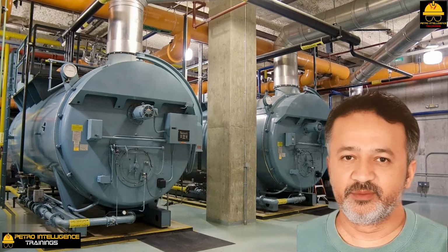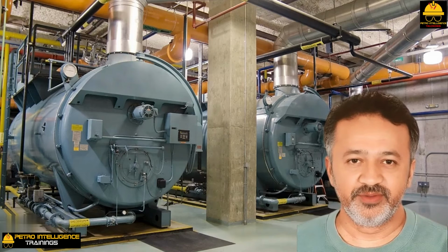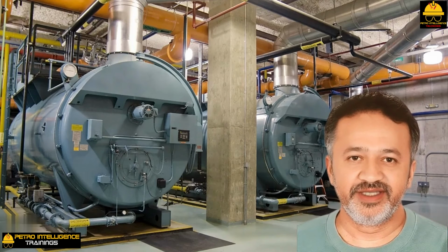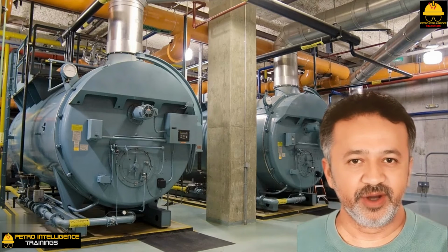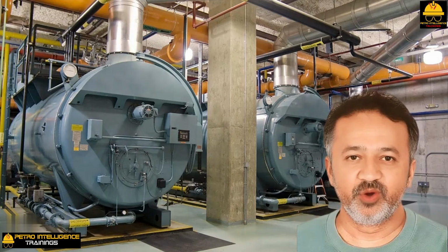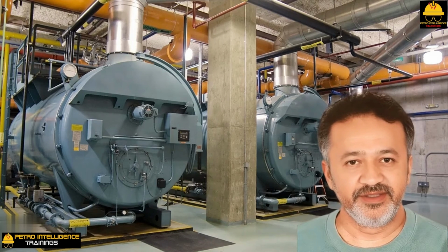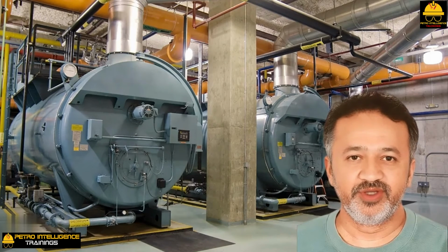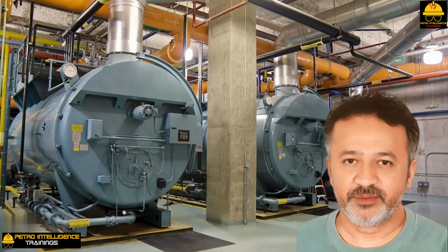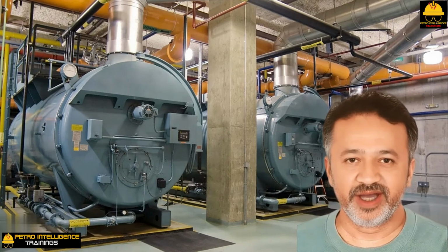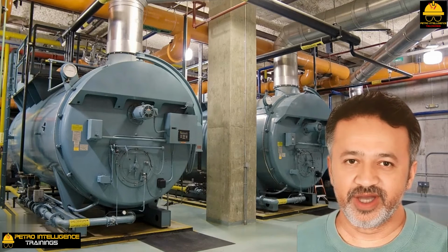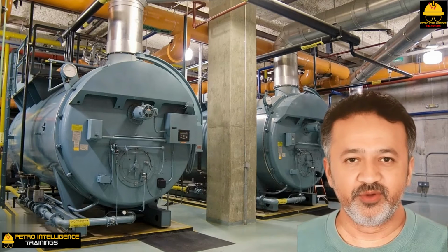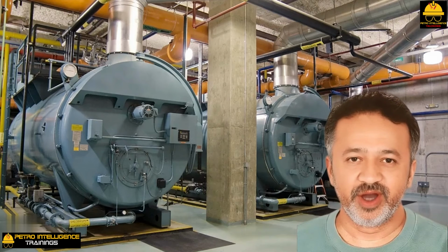Effective air preheat on boiler capacity. One of the first questions that many people ask is: our utility plant operators have observed that when they preheat their boiler combustion air from 20 degrees Celsius to 220 degrees Celsius, steam production drops by around 3 or 4%. They are forced to reduce the firing rate because the radiant section of the boiler starts to overheat. With the radiant section just as hot with or without the air preheat, I would think that steam production would remain constant, so why would it drop off?